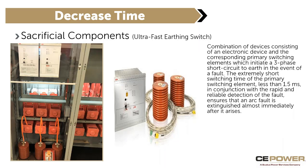Sacrificial components. So in this solution, we're talking about ABB makes a product called the UFIS device, ultra fast earthing switch. It's a combination of devices consisting of an electronic device and a corresponding primary switching element. So what are we doing here? Essentially, what you're doing is you're taking an uncontrolled fault and making a controlled and predictable three-phase fault.